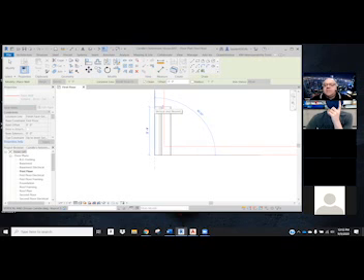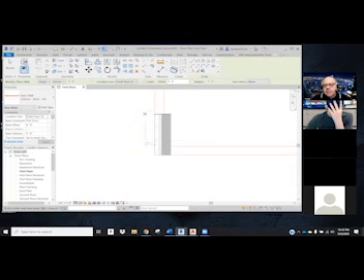So I'm going to pause for a minute here, and we're going to talk about what we've done. If I'm drawing by the exterior, then my rooms become smaller. They become much, much smaller. I'm taking almost 5 inches off of each wall if I draw this way, because my drawing is going off of the exterior. Okay, so I'm going to put that wall here so you can see it. So there is my brick sitting on my wall, and we designed our house based off interior sizes. So I'd have to move this all over. That's a lot of work.